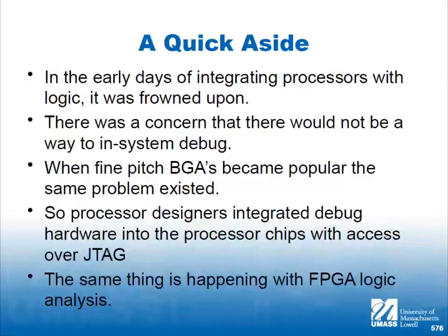So it was okay if they burdened every microprocessor with this debug logic, and then they just had a serial port on it. The test engineers always had a serial port that they used for self-test, and they called it the JTAG port. JTAG stands for Joint Test Action Group. And the JTAG port became the standard way of doing debug and test, but it also became the interface for this internal debug mode for the microprocessors.